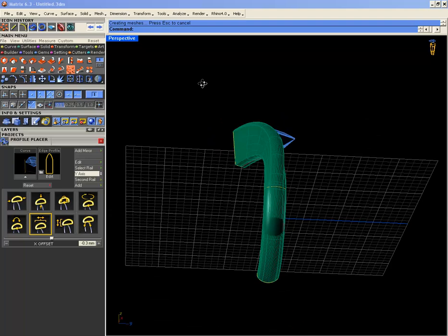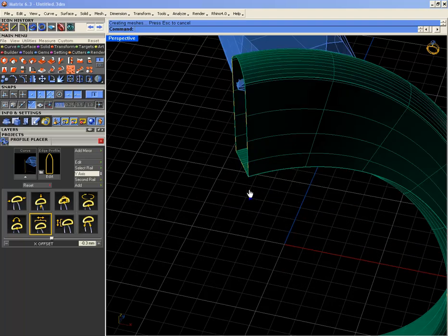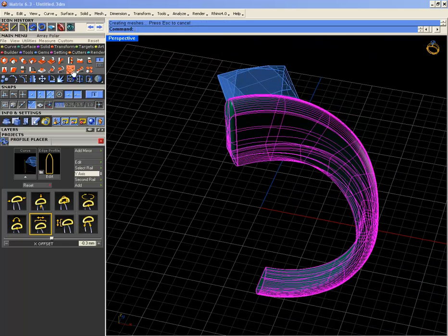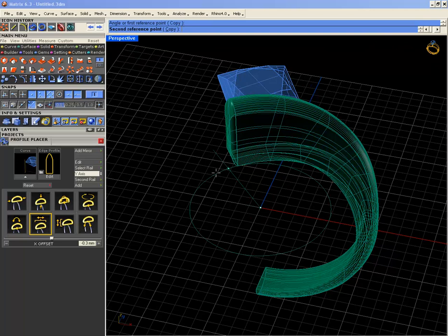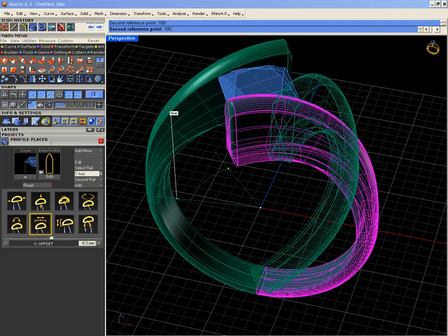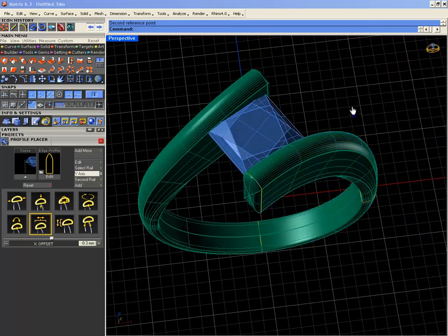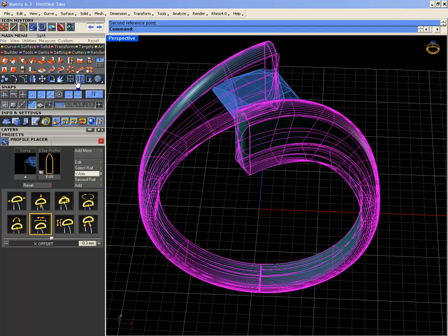Okay, and finally we make a profile curve, profile cap, sorry. Yeah, select them, join them. You can use Ctrl J to join them, or you can do an array polar, or you can simply rotate them. Rotate command, F4, click anywhere, use the copy option here, and 180, enter. There you go. That's it. It's done. Join them together.